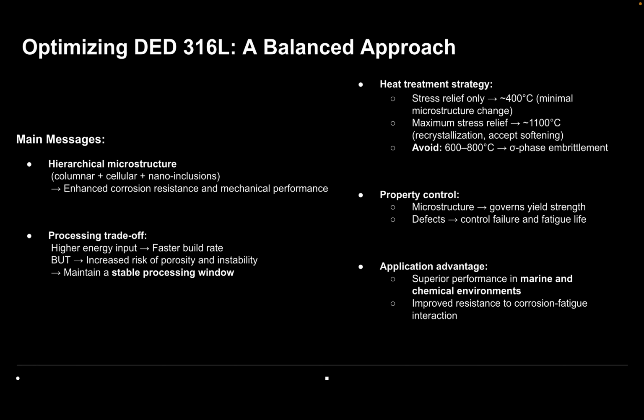Third, heat treatment must be carefully selected depending on whether stress relief or strength retention is the priority. Most importantly, microstructure controls strength, while defects control failure behavior. This makes DED 316L particularly advanced in corrosive environments such as marine and chemical applications.